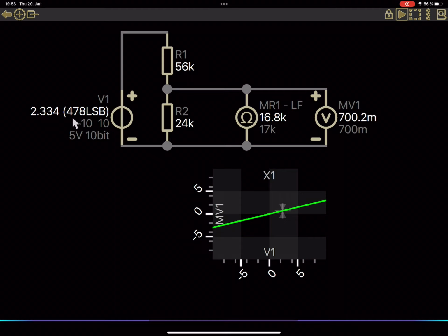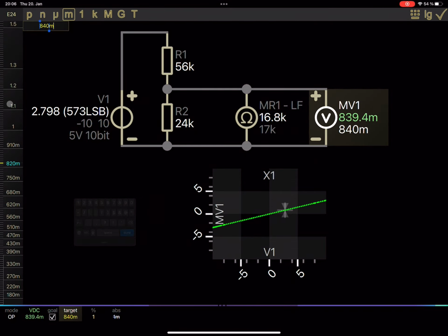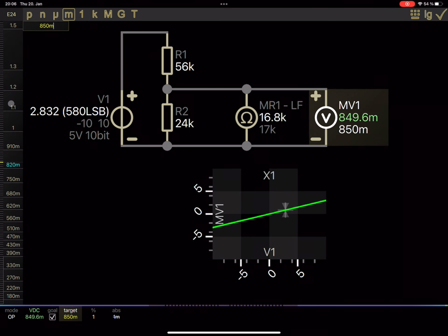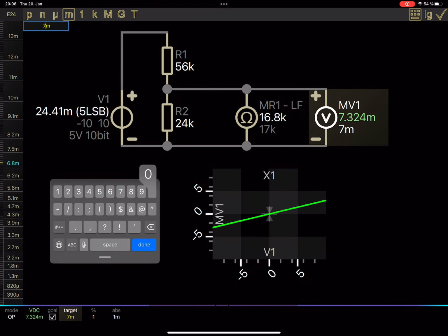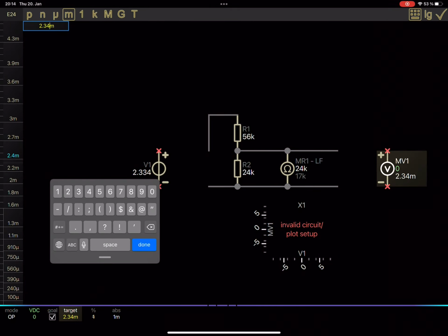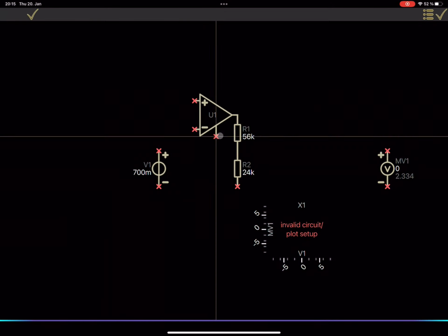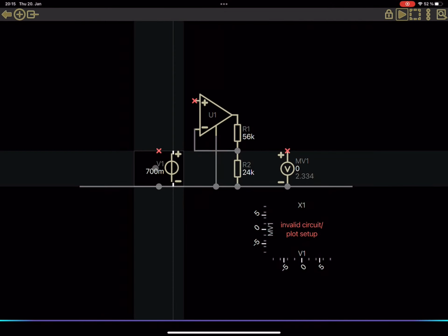For DACs, CircuitShepherd will not only find the appropriate value to fulfill the required design targets, but the digital value which corresponds to the analog voltage is also shown. From an intuitive standpoint, this can be thought of as some sort of reverse voltage divider calculation. This is also the way I like to think of simple non-inverting operational amplifier circuits, as primitive voltage dividers but with input and output swapped.